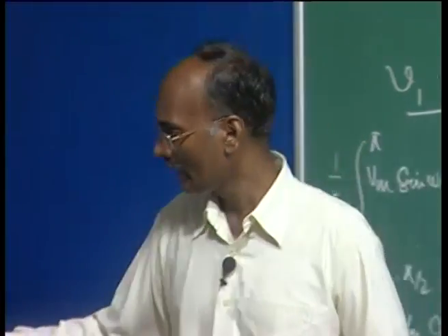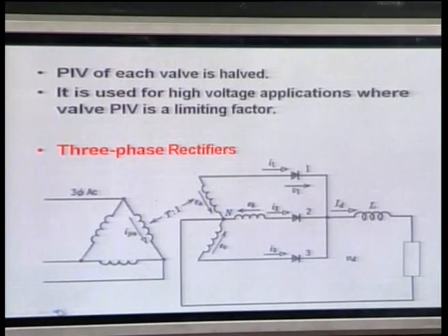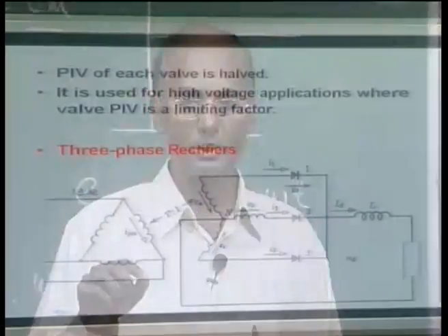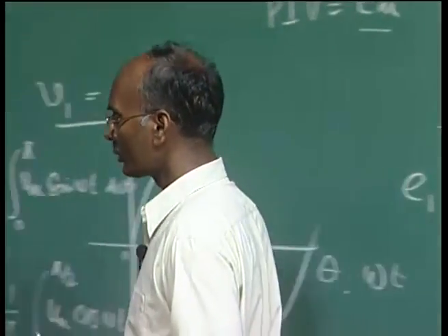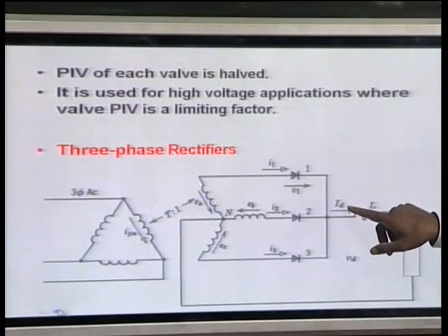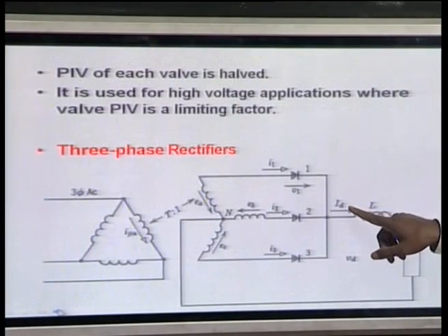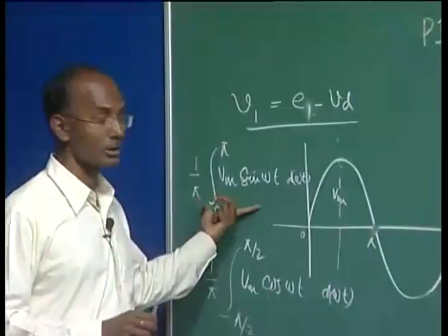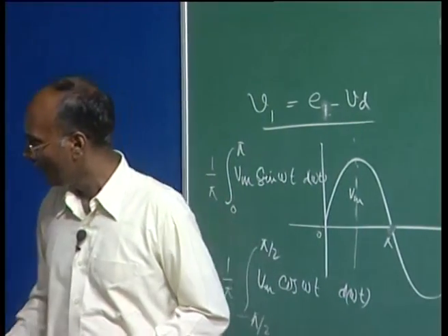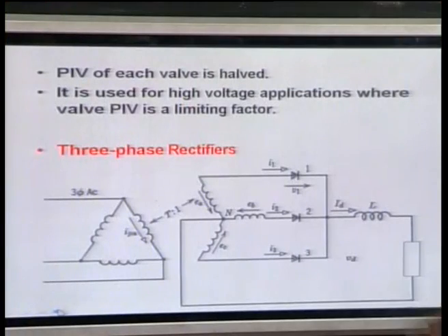instantaneous voltage. Small letters represent instantaneous quantities, and capital letters show the average or DC values. So this ID is shown as the DC current, which is a constant. It is both instantaneous as well as constant. But the output voltage here that we are measuring is VD, which I am calculating here. This is your average value, and that is the integration of this VD, nothing else.